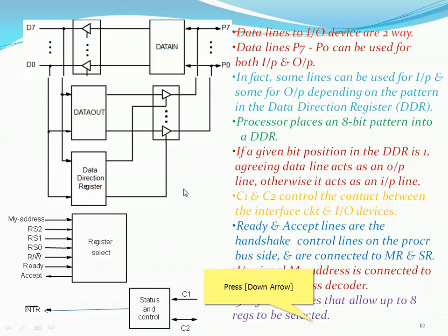3 register select lines, that is, a 3 register select means we have R0, R1, R2. So 3 bits are there. 2 power 3 is 8, so 8 registers you can identify. Here we can have data out, data in, status, and the data register. So the four are there. Like that, if any registers are going to be identified, these three address lines together will be enough. That's why he is saying that the three register select lines can uniquely identify up to 8 registers, right?